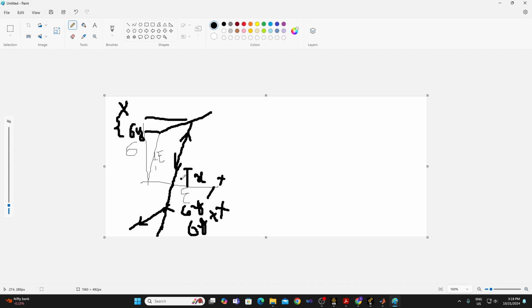Okay, so that origin, the midpoint, has shifted in terms of x. So that's what is kinematic hardening, and kinematic hardening is basically manifested by this shift of origin, and this x then is called the back stress.